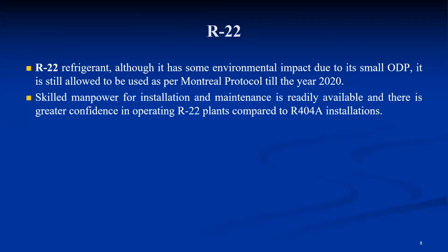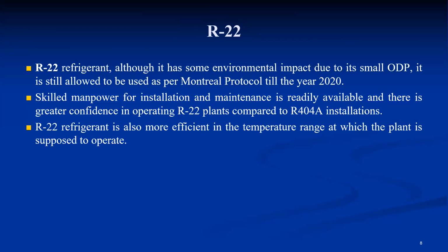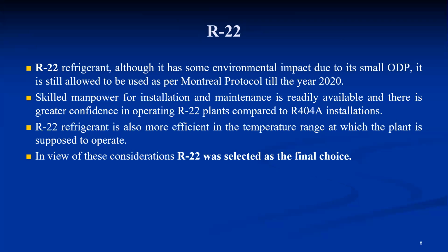So most of the consultants still rely on R22 because of the greater expertise available across the globe. But the R22 refrigerant is also more efficient in this temperature range, because this is a medium temperature application. So for these applications, R22 is suitable at which the plant is supposed to operate. In view of these considerations, R22 was selected as the final choice. This is just a sample case of how to select.